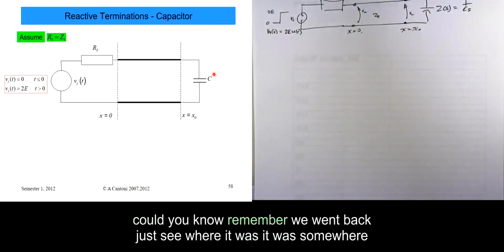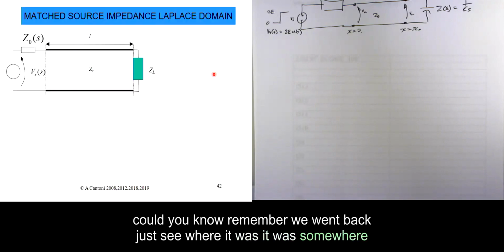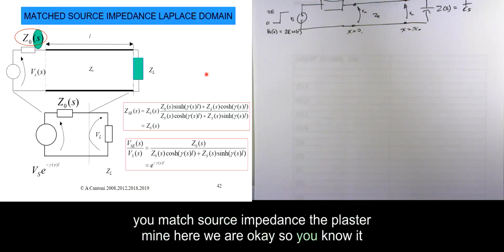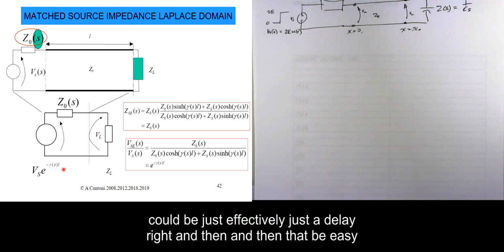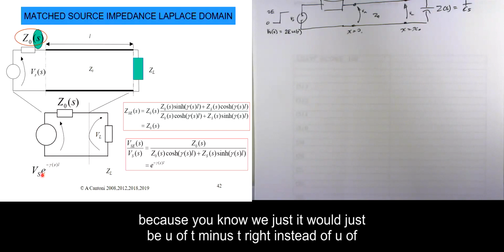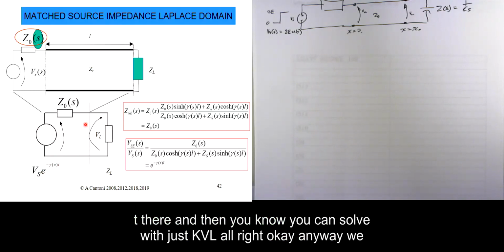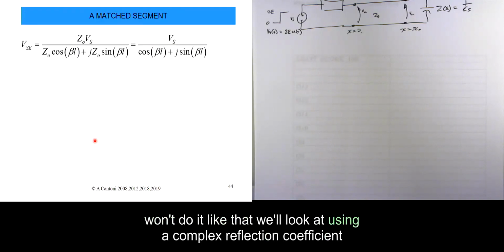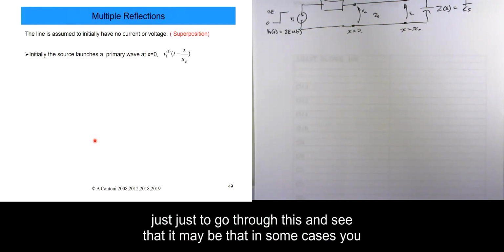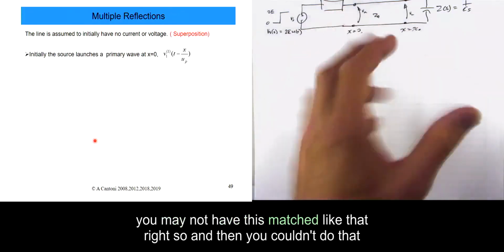So we could do that. Let's see where it was. Here we are: match source impedance, Laplace domain. It could be effectively just a delay, and that would be easy because it would just be u of t minus T instead of u of t, and then you could solve it with just KVL. But anyway, we won't do it like that. We'll look at using a complex reflection coefficient just to go through this and see that in some cases you may not have this matched.